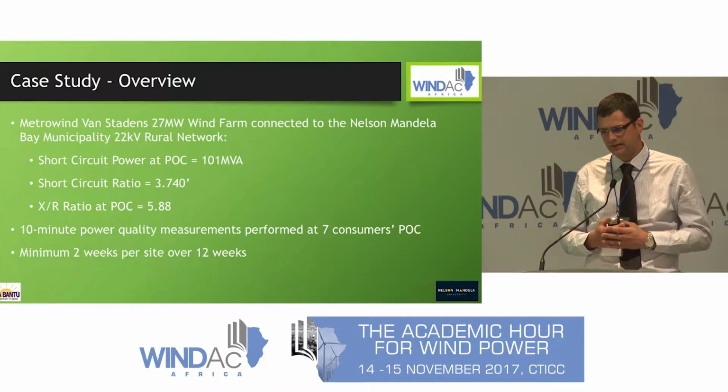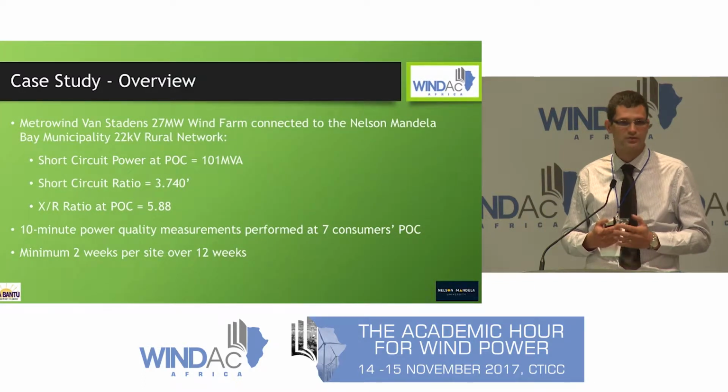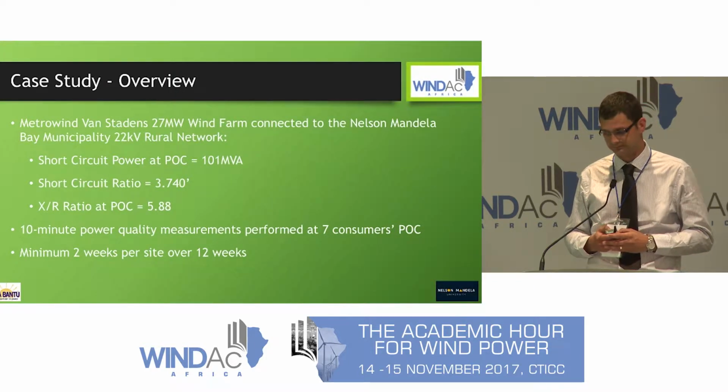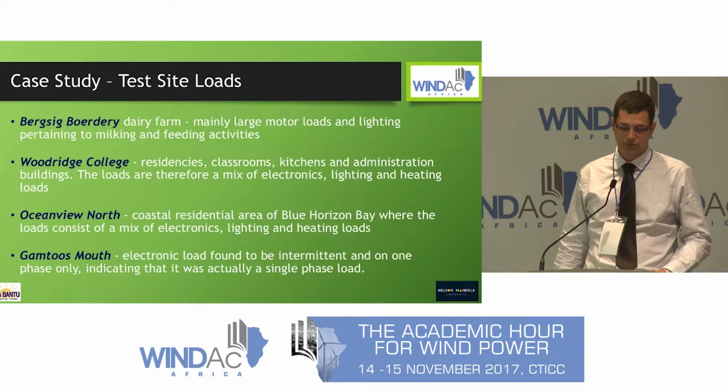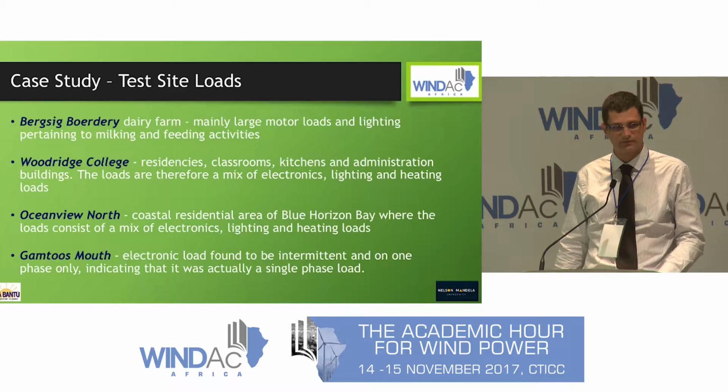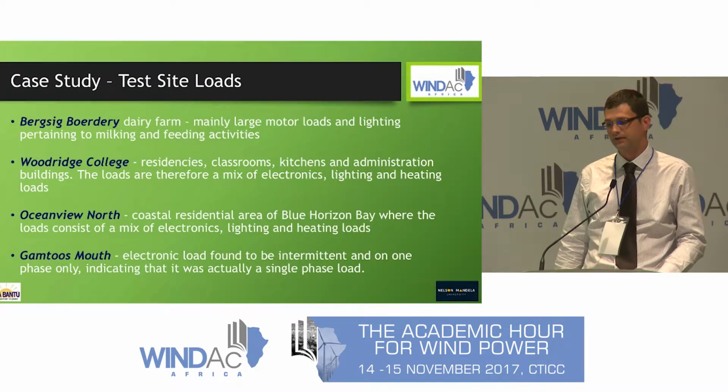The case study looked at performing 10-minute power quality measurements at 7 different consumers' points of connection, each one for a minimum of 2 weeks per site, over a total period of 12 weeks. Here's just an overview of the specific sites and what type of loads were found there.